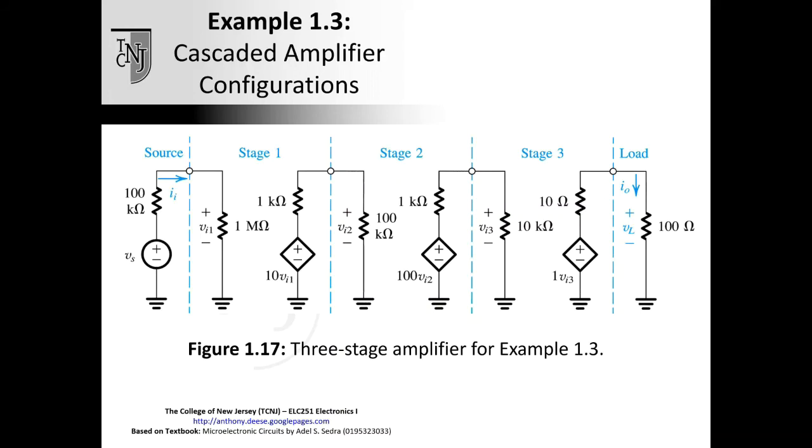So the ratio between the input resistance and the source resistance for stage 1, there's only a factor of 10, but I guess that's the rule of thumb they're using, so it's good. At least it's not closer than that. And then for stage 3, again, a factor of 10 separation. The output resistance is 10 times lower than the load resistance. 10 is 10 times lower than 100. Okay, so this is the example they're giving us. I'm going to say, okay, fine, we'll go with it.